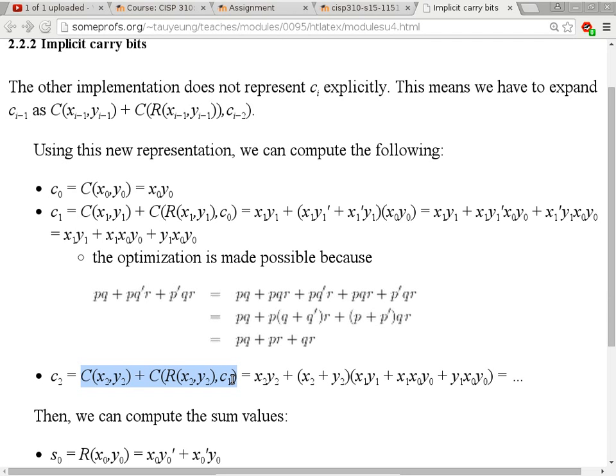So it doesn't have the propagation delay that we have with the traditional design of using full adders anymore. When you do it this way, you're not stacking up full adders anymore. You're basically using complicated equations all the way through in order to speed up your adder. Will it be pretty much right away by the 63-bit too? It's not right away because it will still involve more AND gates and NOT gates, but it will be much faster than relying on the carry bit to propagate.